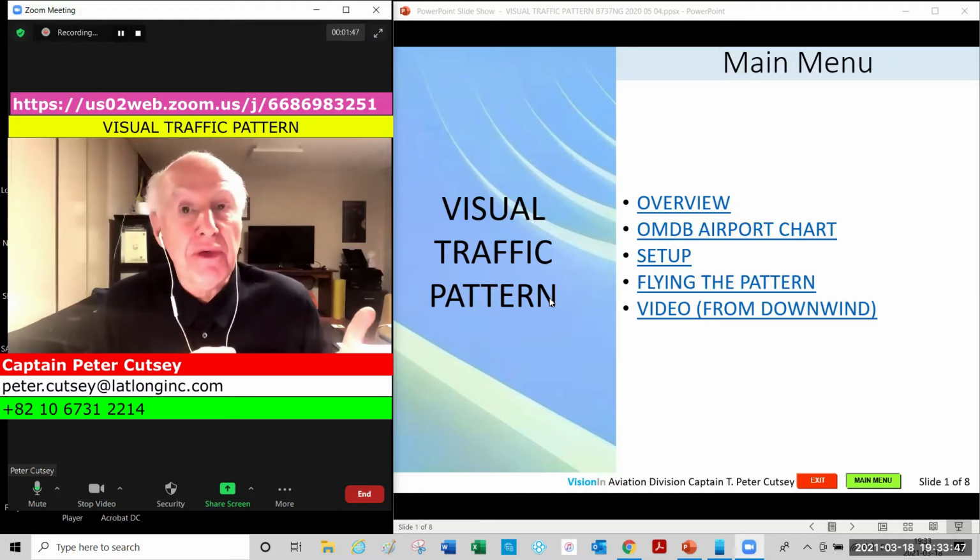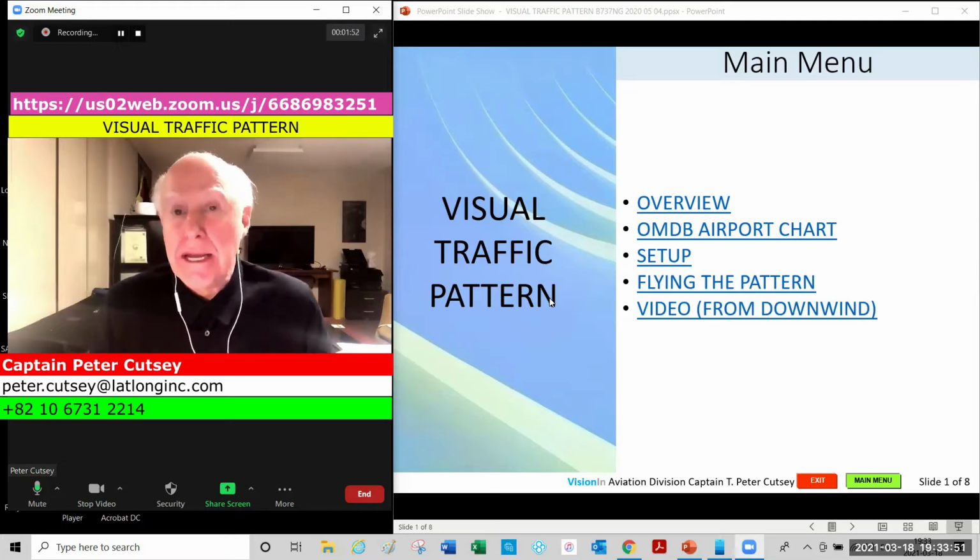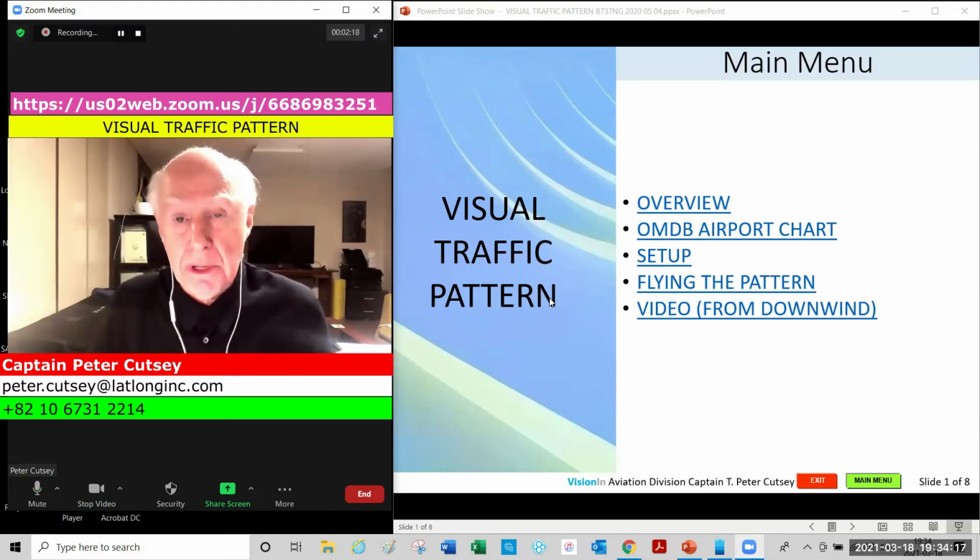You remember my briefing on the cake and icing? Remember, the cake is the raw data and the basic part of flying, and the icing is the magenta. We're not going to use any magenta for this particular maneuver. It gives the pilot an opportunity to understand the very important relationship between thrust, pitch, and trim. Very, very important. Let's get right into it.